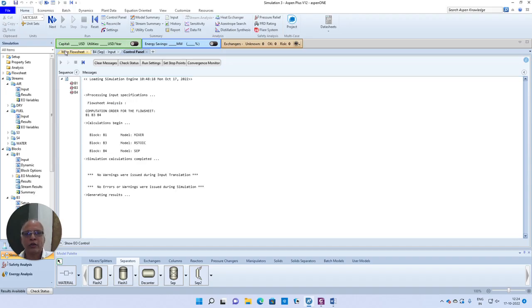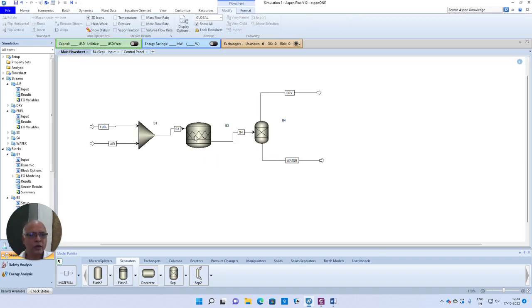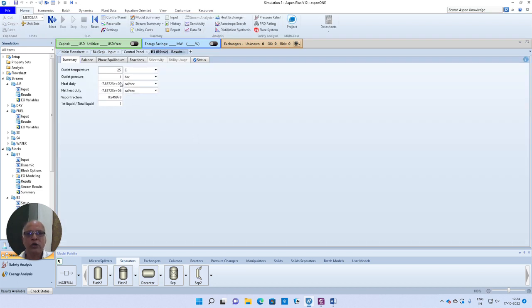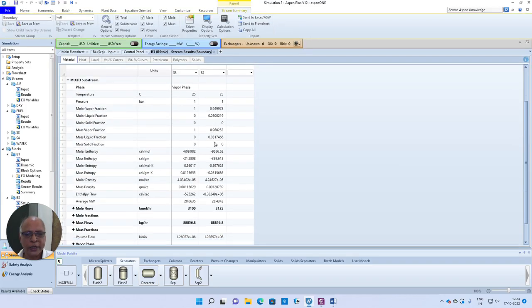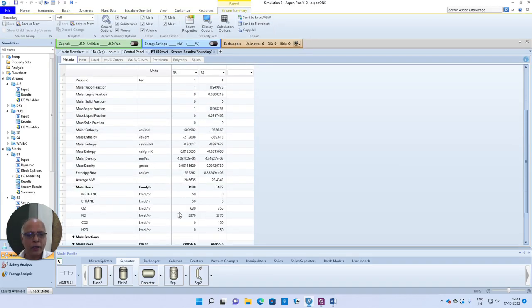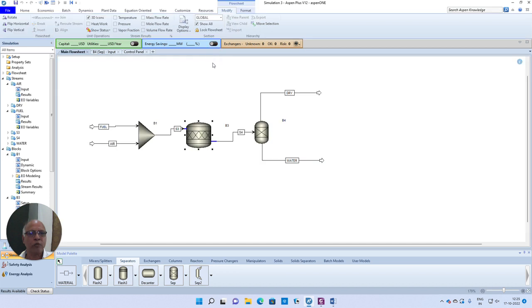Yeah. So let us go and see the results. For example, let me see whether whatever we have assumed with respect to air flow rate is enough for us to completely convert methane and ethane. So you can see all the methane and ethane is completely converted. Of course, we have given a lot of air, because roughly only 50% is consumed. 630 out of that, 355 is still coming out. So we may have to anyway adjust this based on the composition.